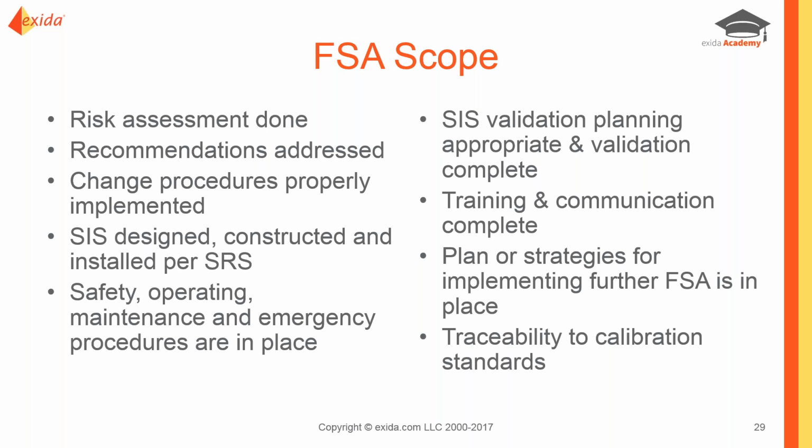The last point there, traceability to calibration standards. Any tools that we use for calibration or testing of equipment, we need to have that traceability so that we know that the measurement devices that we're using to check the health of the system are indeed themselves robust.